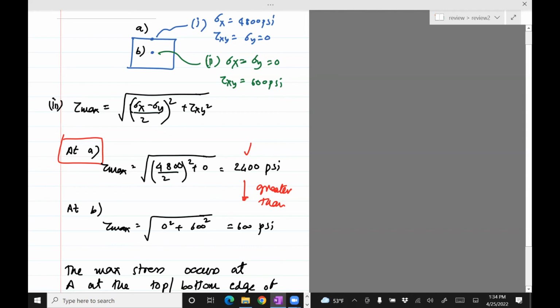So the formula we will use is the one for sigma A and sigma B, right? Yes, that's in the equation sheet. You use sigma x and sigma y in order to find the principal stresses, and those principal stresses are sigma A and sigma B. Yes, that's right.